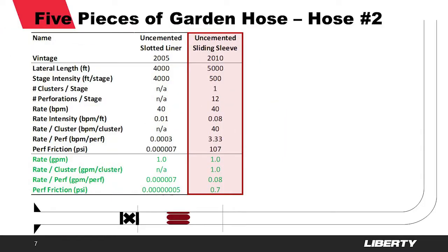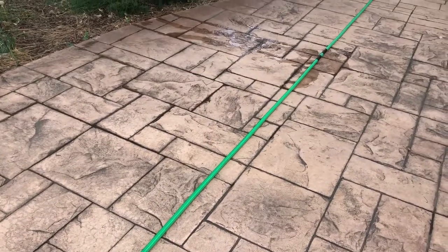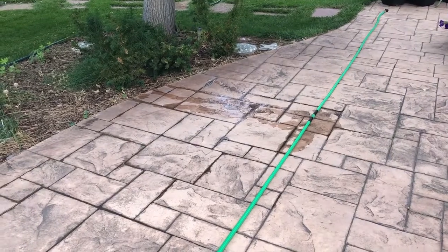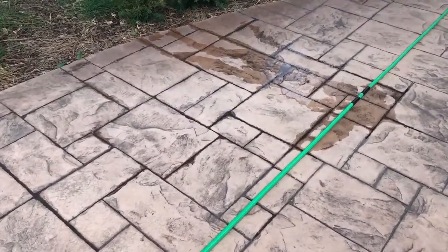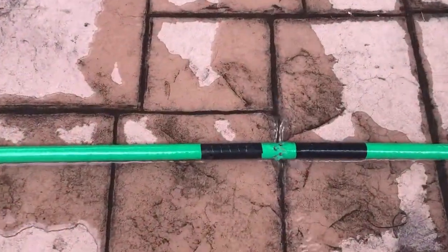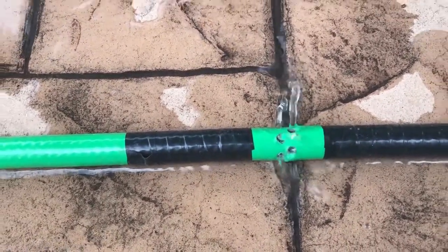Well design number 2 is a sliding sleeve design with external swell packers in an uncemented hole. This design was used in the early days of the shale revolution, especially in Williston and DJ basins. The main benefit of the approach was that the sleeve could be shifted with a ball during the frac job. This was good for service companies to keep their equipment busy during early development with mostly single well operations. The strategy uses relatively low rate, 40 barrels per minute, with gel into an open annulus.